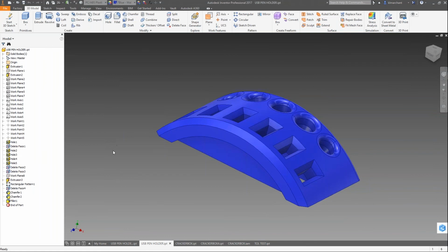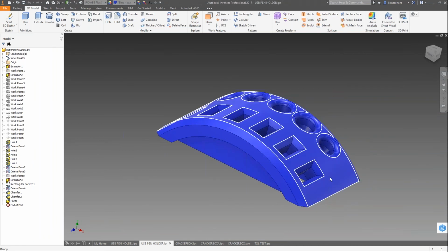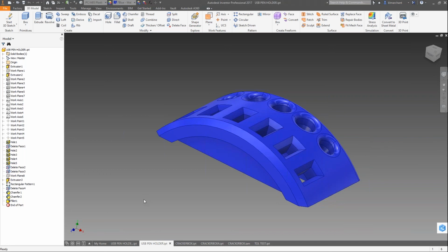So hopefully if you had any questions, this gave you some good ideas, some good starting points, and a little bit of clarity on how to take a part that I machine or manufacture for the real world and get a successful print out of it. Kind of a quick overview: wall thickness, resolution of the nozzle, and overall surface contact to the print bed, and that leads into the heat transfer. That's what will cause the warping and whatnot, all the way down to how small of a detail I can get away with on my printer. And that just depends on the technology and or the hardware specifics of your printer.